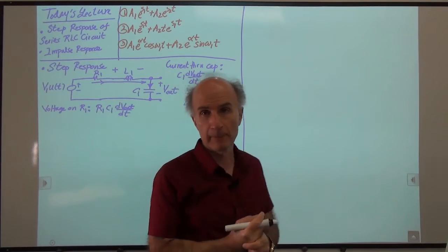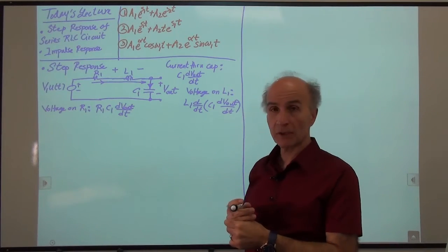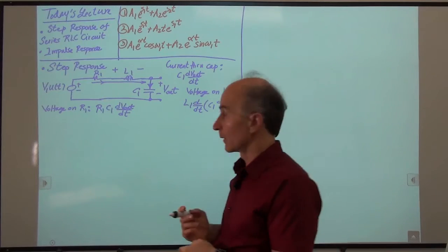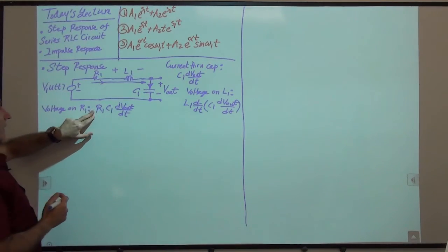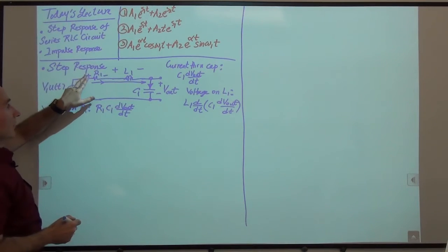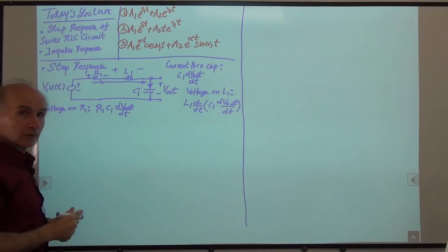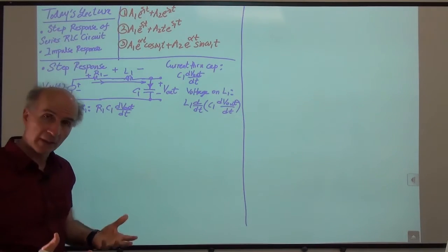All right. Okay. How about the polarity of the voltage across R1? Because the current is going from left to right, and I have a positive sign here, I will have to pick plus here and minus here, from high potential to low potential. All right, so now we have all the voltages, we can write our KVL.